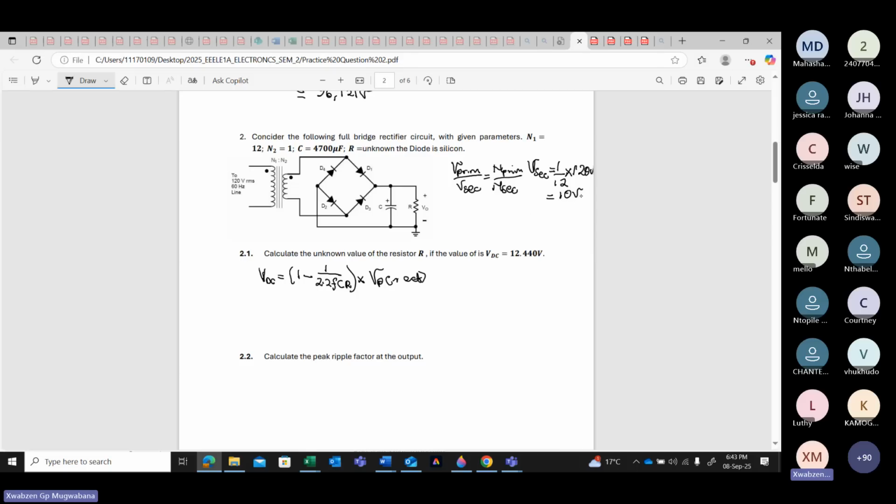These volts that I'm getting, it is my RMS. Are we together? Then from there, I can say V peak secondary is going to be this voltage here multiplied by root of 2, isn't it? If I multiply this voltage by root of 2, what do I get? 14,142, which means that is the voltage that I get.